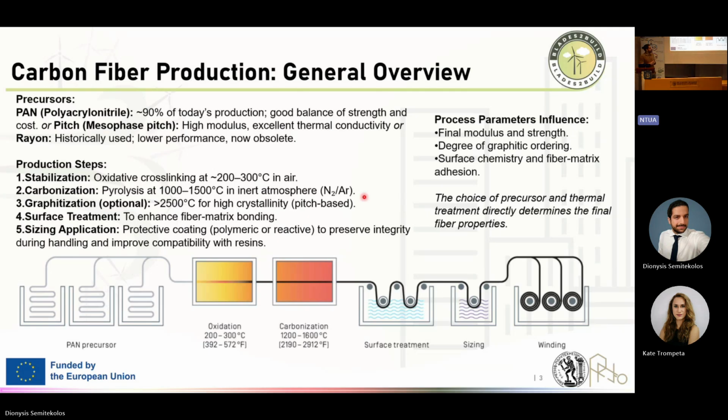Why do we do that? Because you can understand that a fibrous material doesn't have properties in all directions, and also it is not a stable material. You can bend it, twist it, do many things with it. You can for sure put tension on it, and it's going to have good properties. But if we combine them with resin and make adjustments on the design and on the direction that we put those fibers, we can have exceptional properties in more than this one direction. And this is why we use them within the resins to produce the composites.